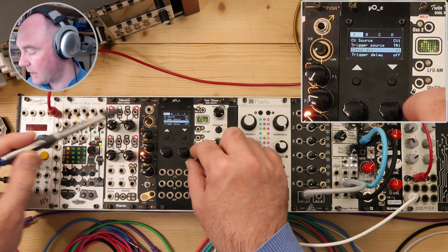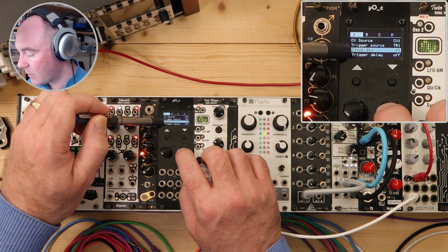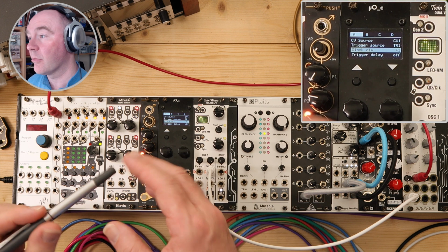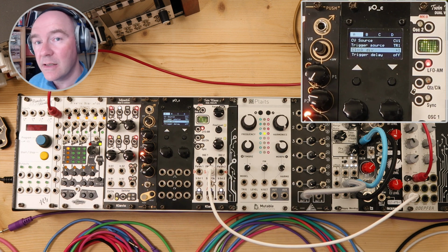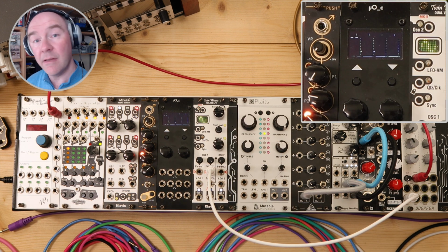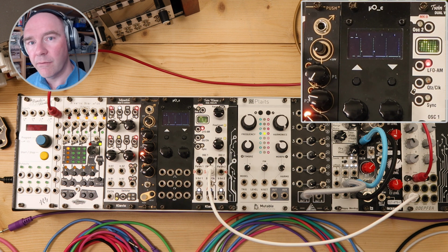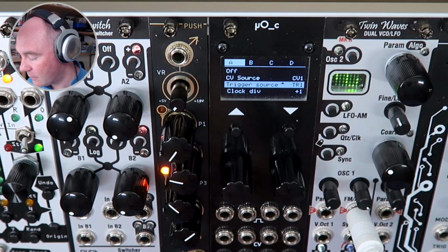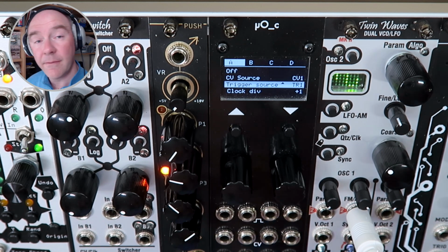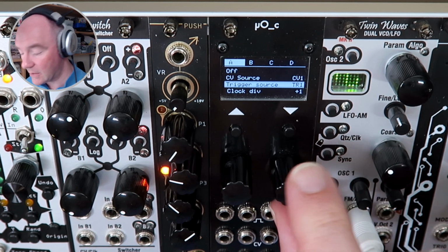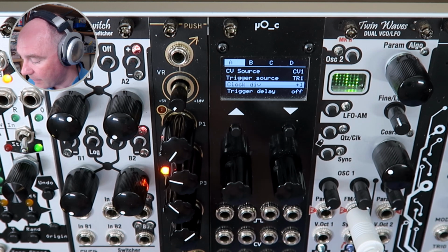You can also divide down the clock. So this means that quantization happens on a certain number of clock divisions. This is very handy if you want to have the same CV source going to multiple oscillators, but at different rates. So for example, for every clock tick, you'll send a new note to a lead oscillator. Every 4 clock ticks, you would send a note to a different oscillator, maybe a chord or a bass line to change. So that's a very useful feature for building musical progressions.